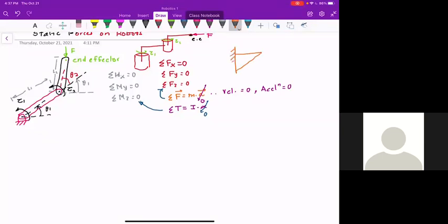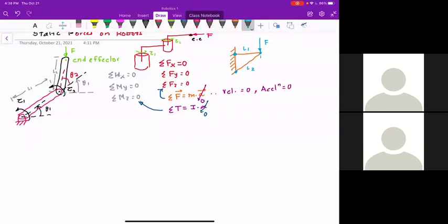So you have a truss, and then you have some load F. And say what you want to do is find out the loads in the link L1 and the load in the link L2. And assuming these are all hinge joints, what you do is you resolve the forces in X and Y direction.